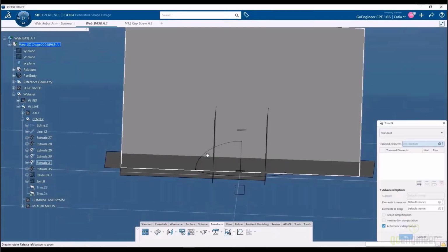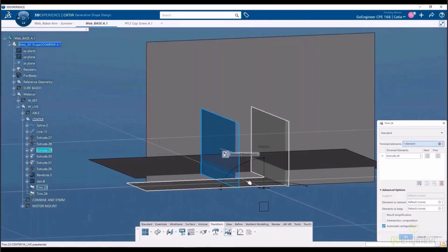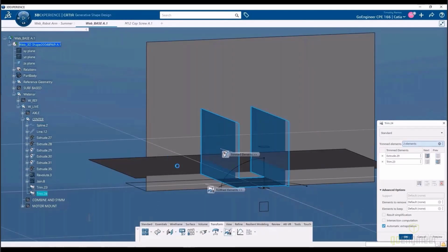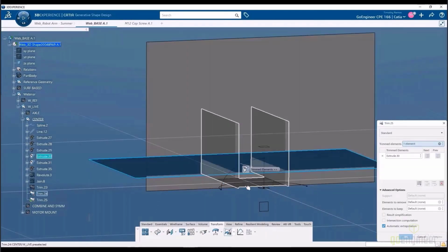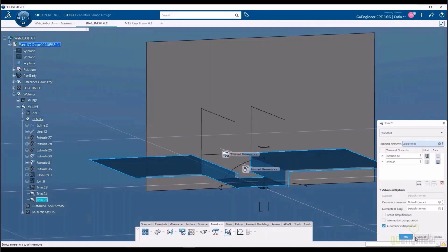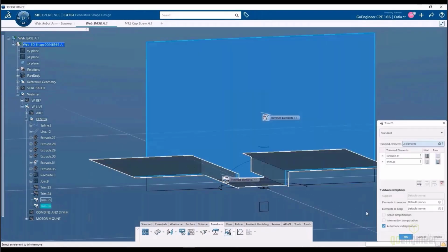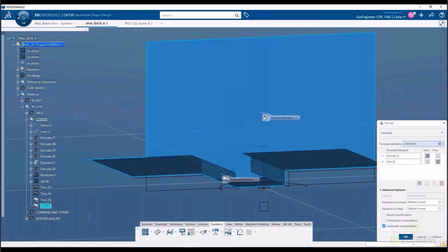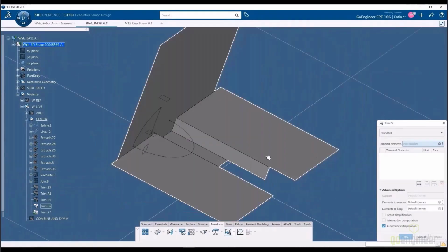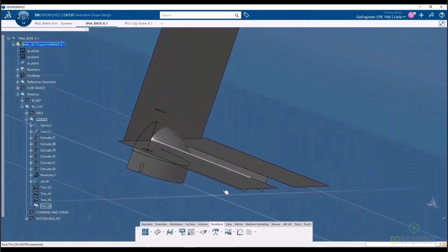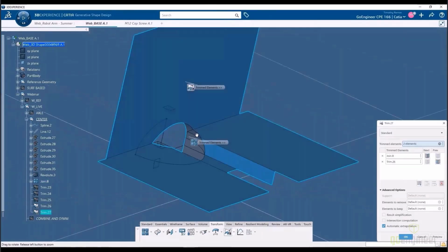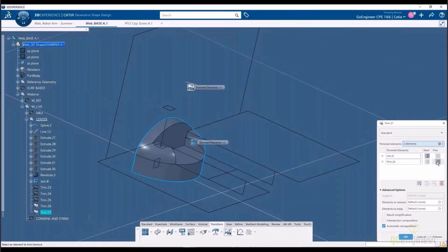Now, keeping that in mind, we can use more than two surfaces in a singular trim command, but in the case where we might have to update this model down the road with the possibility that our solutions might switch, it's just easier to correct that scenario when we just do the trims one by one. So here we see toggling through our solutions until we get the desired result.